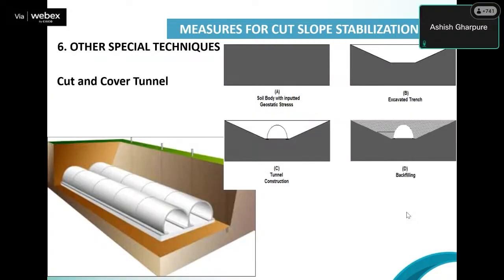So some special methods people are using, and presently with NHAI projects also, the cut and cover tunnel. Where the depth of the tunnel cannot be too deep, we all know 2D to 3D overburden is required to make the tunnel. But such overburden is not there. In that case, also a tunnel can be constructed like cutting off the entire thing, building the shell of the tunnel, and then refilling it back, so that you don't have to permanently acquire the top land if it can be filled back and used.